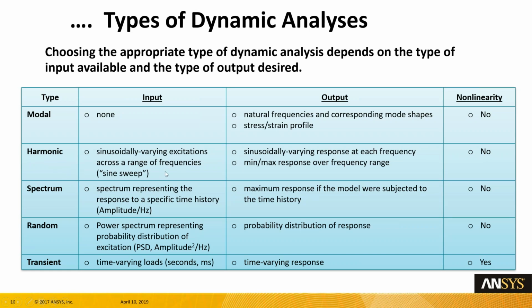Harmonics. A harmonic simulation is done in the frequency domain. The inputs are any sinusoidally varying excitations, like force or displacement. So any loads that vary sinusoidally could be an input. And the output, of course, is the sinusoidally varying response of the structure at every single frequency. And again, there's no nonlinearity.